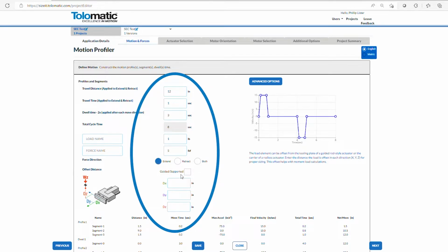Now, here's one place that gets overlooked quite a bit, guys. I've reminded you before, and I'm going to remind you again. If you presume you don't need to support the weight of the payload as it extends out, keep in mind that if you don't support it somehow, especially in a horizontal application, gravity pulls down on that, and it pulls down more as it extends. So you're stressing that ball nut or that roller nut or that Acme nut.